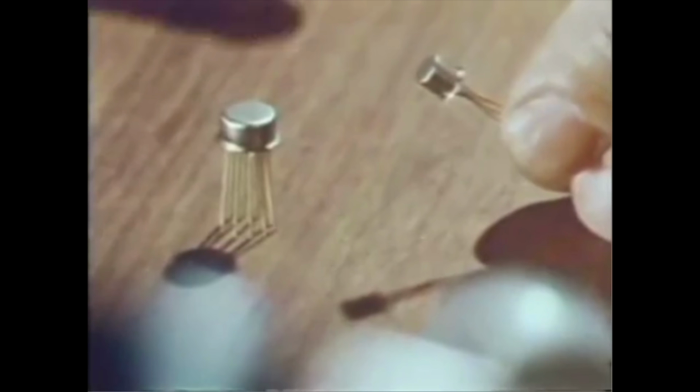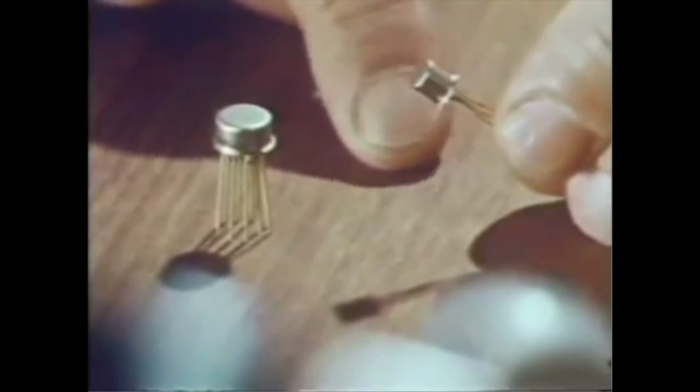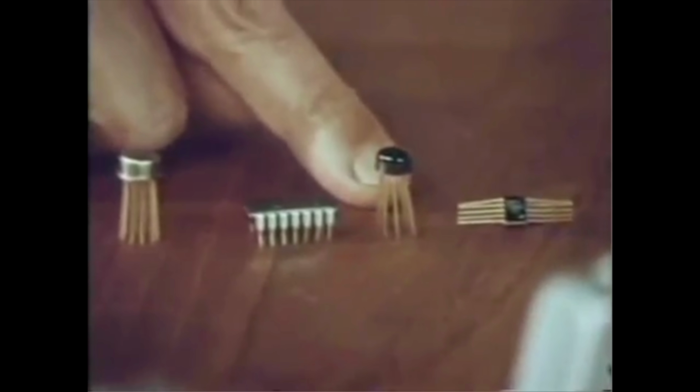In the old days, it was simple. You had a wide choice, two, large and small. A TO18 outline, small, and the TO5 larger outline. These days, we have upwards of 250 varieties of packages, and a user can select any one of them. Here are an example of three of these. A dual inline package, a plastic package, and a flat pack. The most nearly universal of these is the dual inline package. Let's take a closer look at just how that is made.